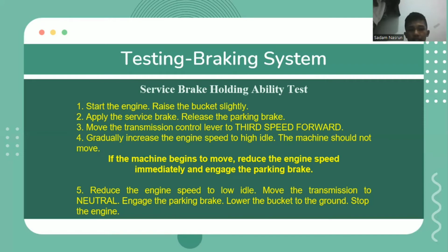Please pay attention. If the machine begins to move, reduce the engine speed immediately and engage the parking brake. Okay, number 5, reduce the engine speed to low idle. Move the transmission to neutral, engage the parking brake, lower the bucket to the ground, stop the engine.